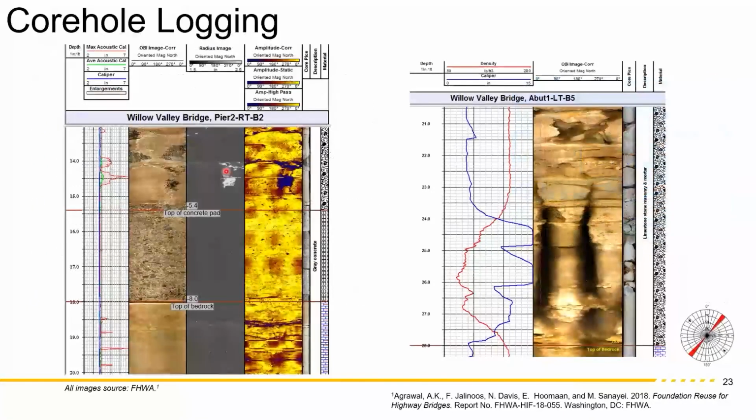So in the next slide, the first one shown is the optical televiewer. We have the optical camera that you put down the borehole. The tool has a 3-component magnetometer, similar to the magnetometer that Bernie used, to correct for the changes in azimuth as the tool rotates as it goes down the core hole.